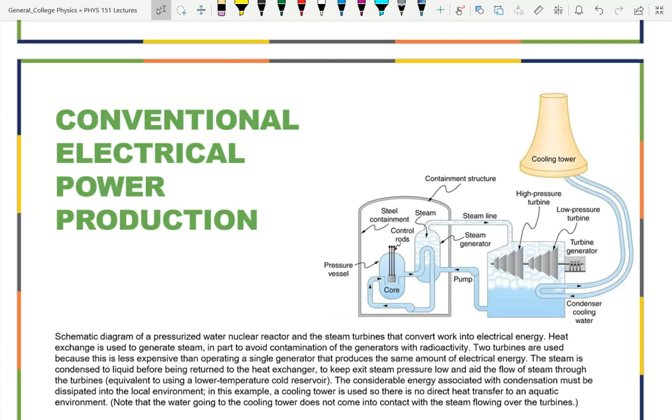Something has to generate the heat to boil the water. And then that hot water is going to be used to drive steam turbines. Steam turbines are more efficient than pistons. That is, you can adjust the pitch of the turbine so that you just keep pushing and pushing and pushing until you've used up virtually all of the higher pressure, the pressure difference, and you exhaust a much cooler gas, steam.